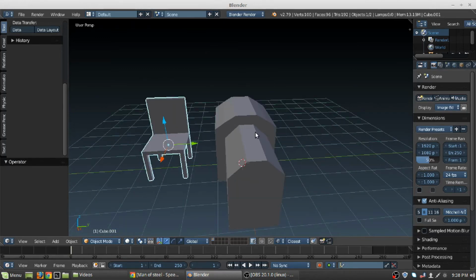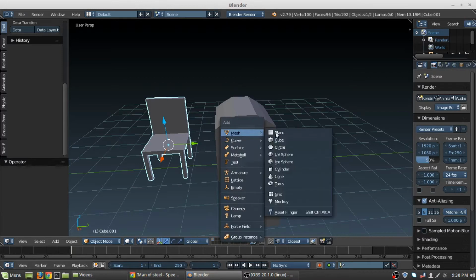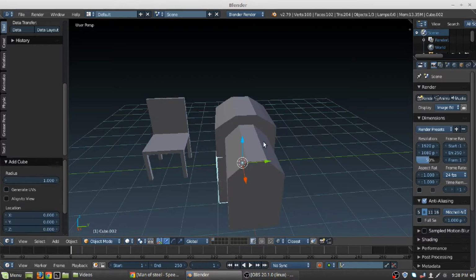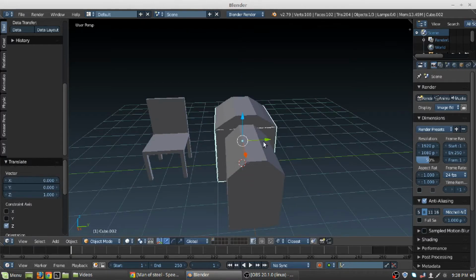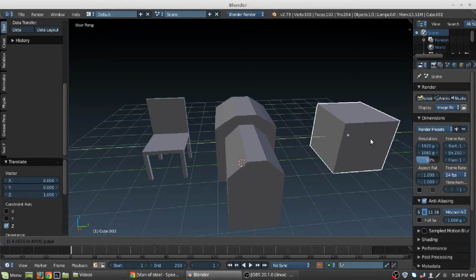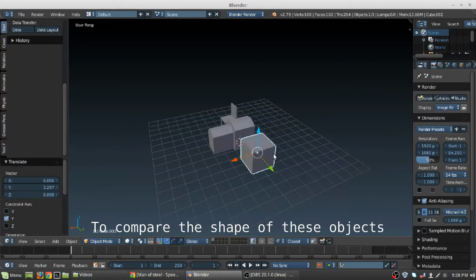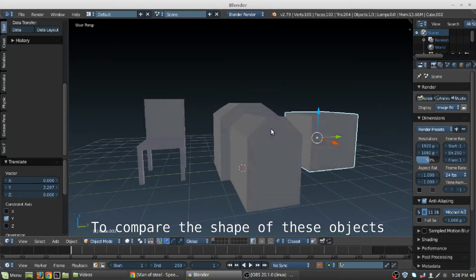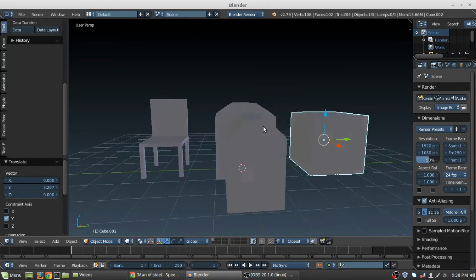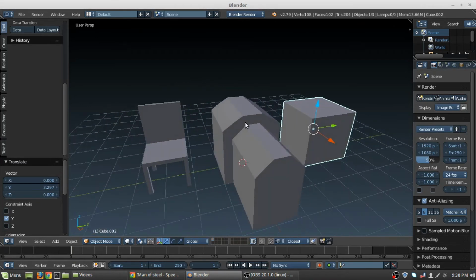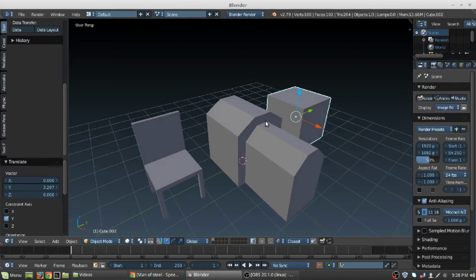And let me just really quickly create another box and bring that up in the z-axis and bring them out, to show you how from a box we just created two entirely different shapes just by modifying and editing the mesh. Now this is how modeling is done. Now let's move on to the next stage.